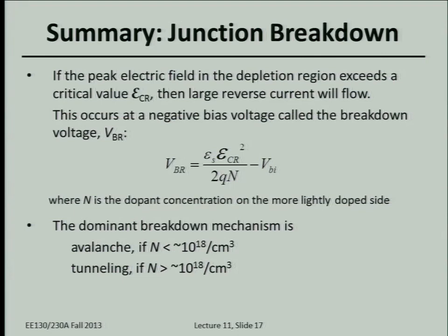So what effect does an electric field have on electrons? It exerts force, right? Electrostatic force. So if the electric field is really large, that means you're exerting a lot of electrostatic force on the electrons that are covalently bonded. Right? So now you have, in the silicon, covalently bonded electrons, and a high enough electric field that you can actually just rip the electrons directly out of the covalent bond.